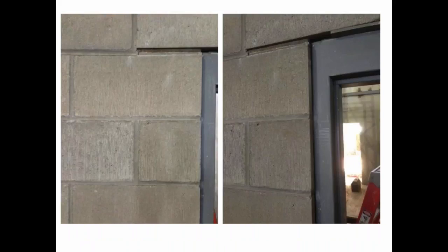That even looks worse. So we have to get comfortable and familiar with how to design bearing plates. You, in fact, never should see a bearing plate. So as you maybe have to do a steel lintel, still the bearing plates never should come to the edge of the wall. So that's a little tip for a different day. You know, you should never see those in your designs.